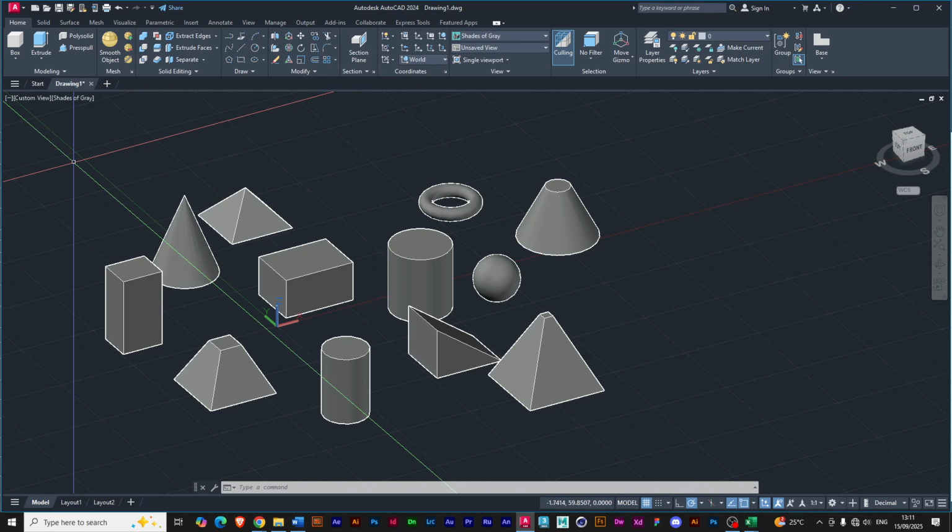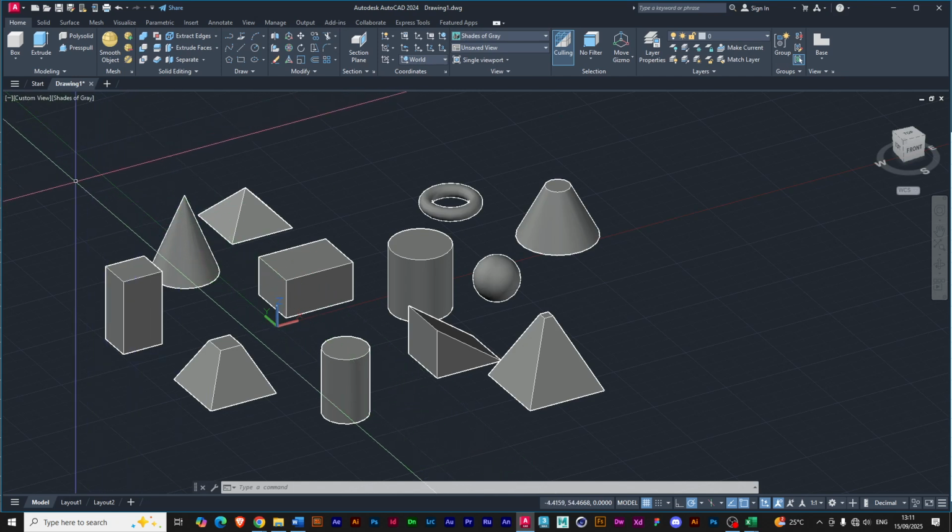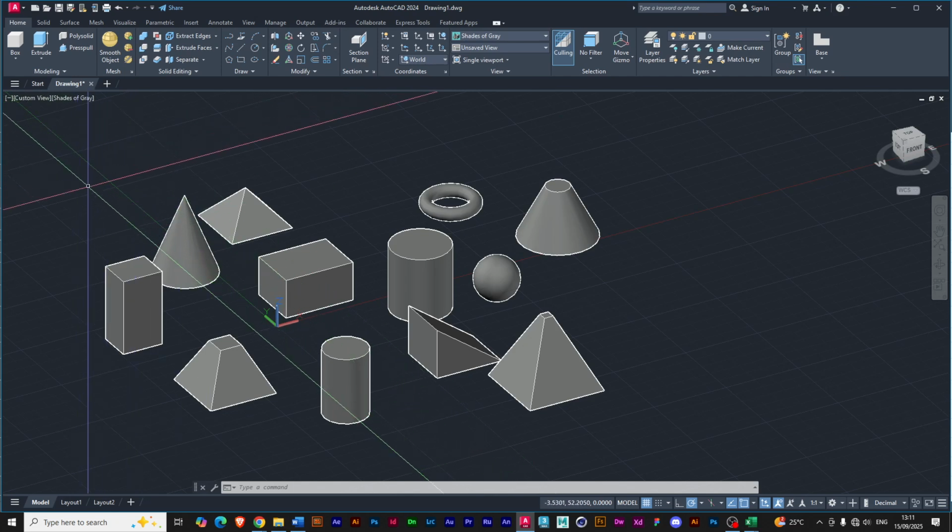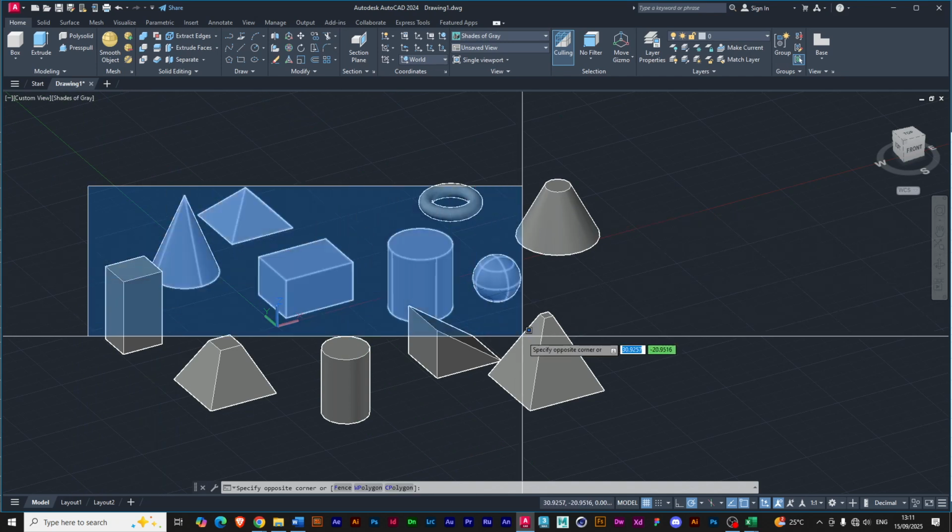The blue marquee only selects objects that fall into that marquee. Anything that isn't completely engulfed by it will not be selected. The green marquee is called the crossing marquee; it selects anything it touches. So like now, I click somewhere in the empty space and drag to my right, a blue marquee.